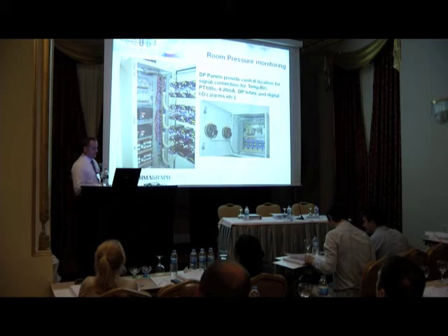We have a unit which provides 4 to 20 milliamp inputs: temperature, RH, differential pressure, and 4 digital inputs, the door switches, or it could be equipment failure. One of the other things we do is work in the IVF industry, and they have some equipment which, as well as measuring temperature, has fault conditions, etc. So we can just take an input there and say if it's healthy or unhealthy.